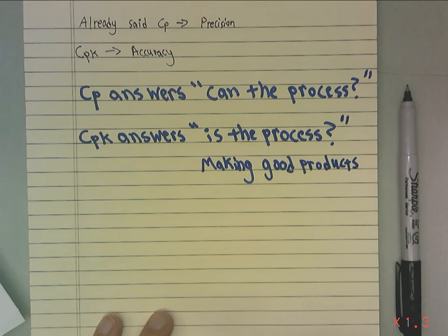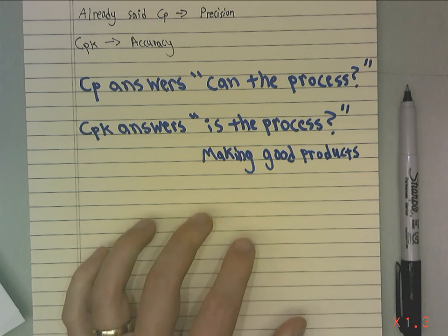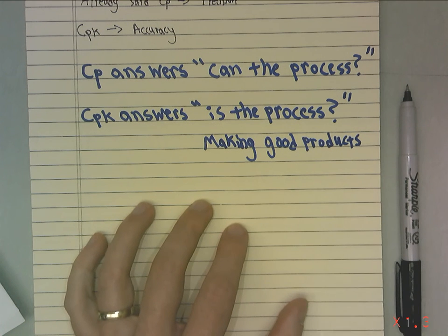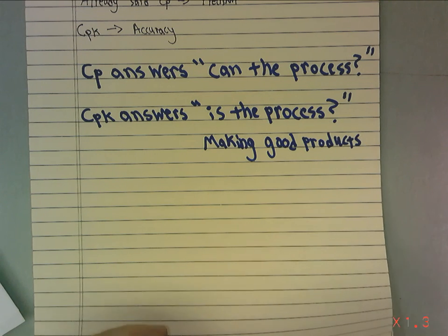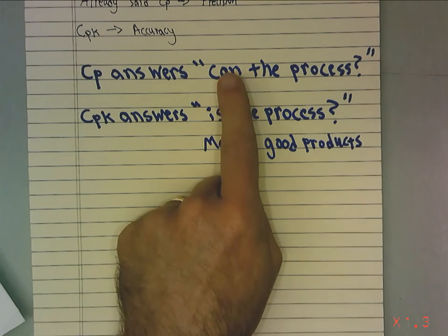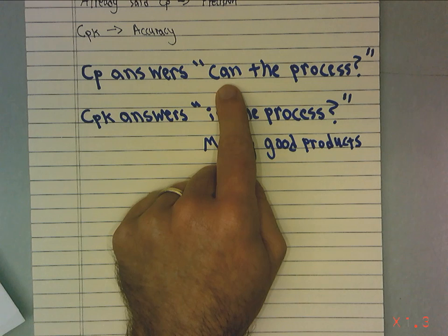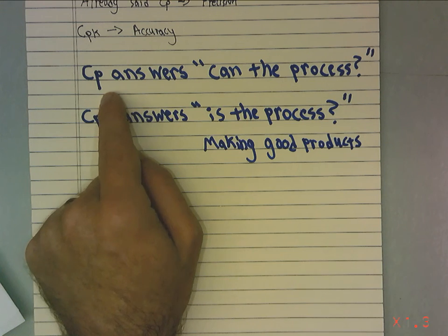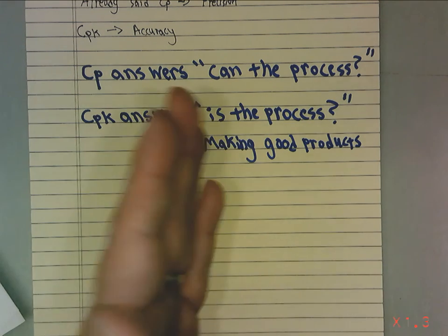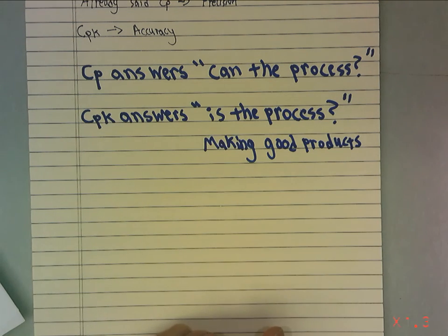Right, so if we've got standard deviations for the different processes available in our facility, an engineer that's doing design can give us a tolerance and say what processes can we use to make this product. Well, we can go through and do the calculations and say, based on process capability indexes, these are the processes, X, Y, and Z, that can be used.